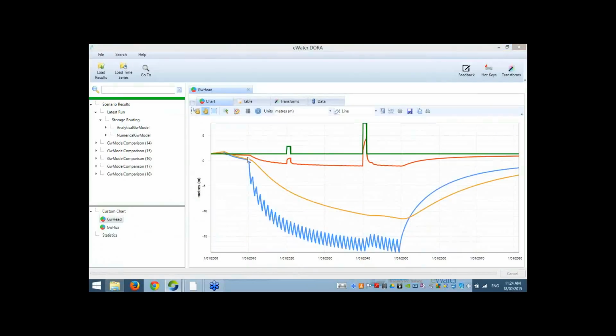Next we're going to hand over. Yes, diffuse infiltration. So the question is, can diffuse infiltration be used for infiltration from irrigation? And the answer is yes. You can inject that directly to the aquifer via the direct diffuse source. And you can choose the spatial domain over which you inject that infiltration as well.